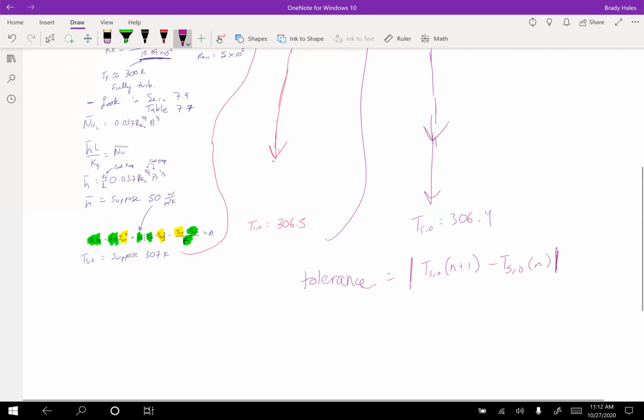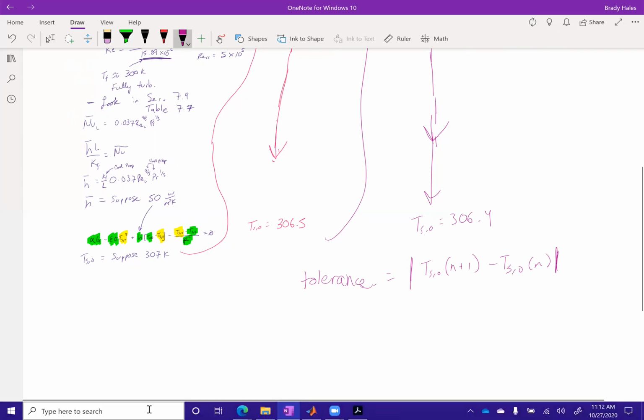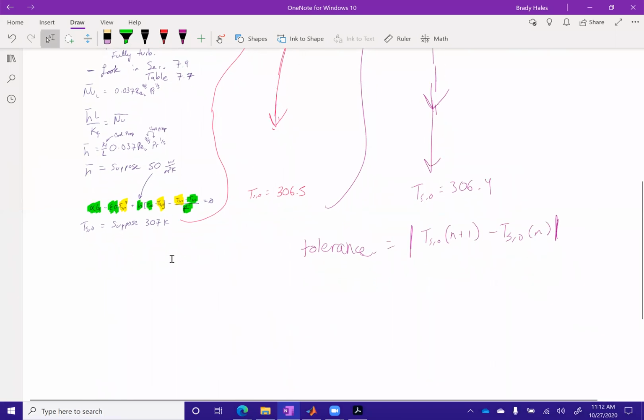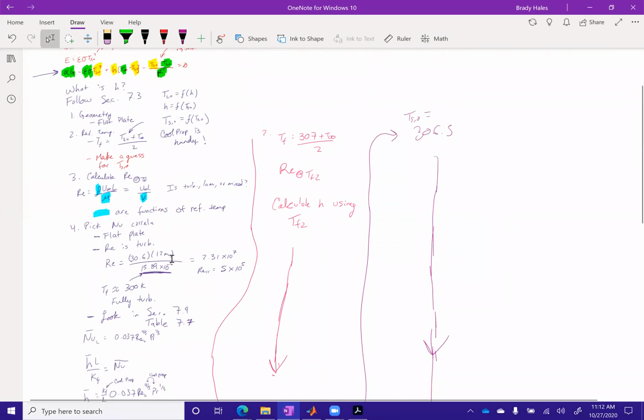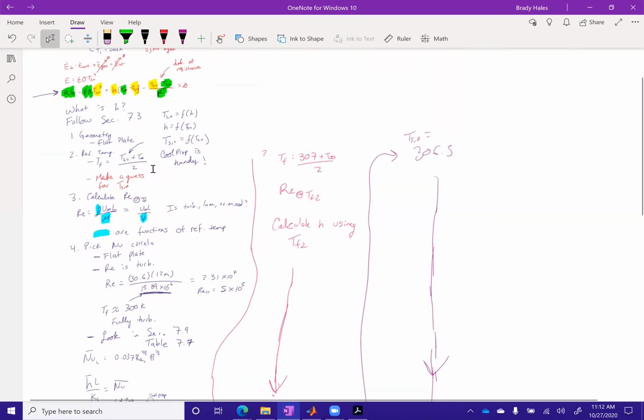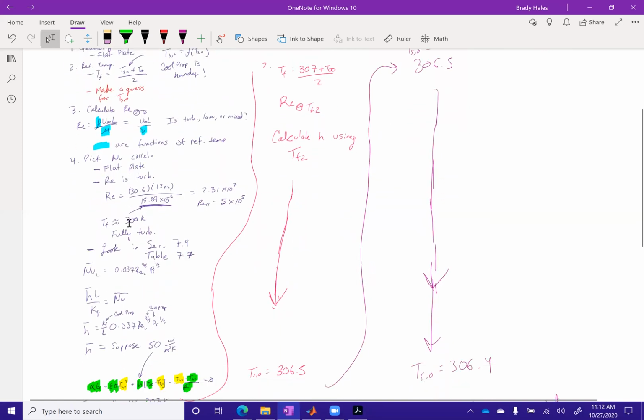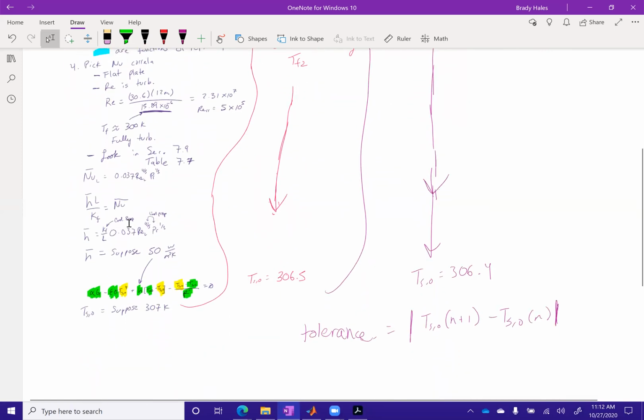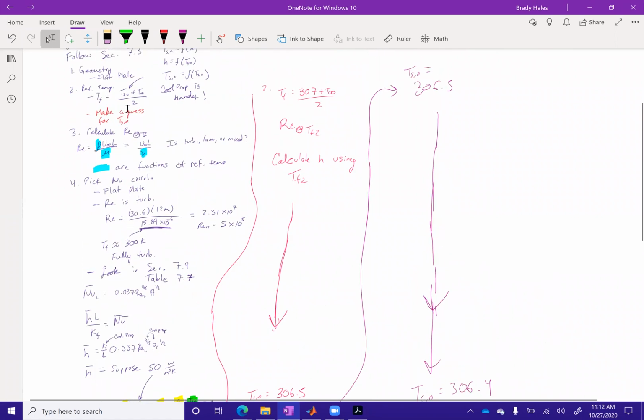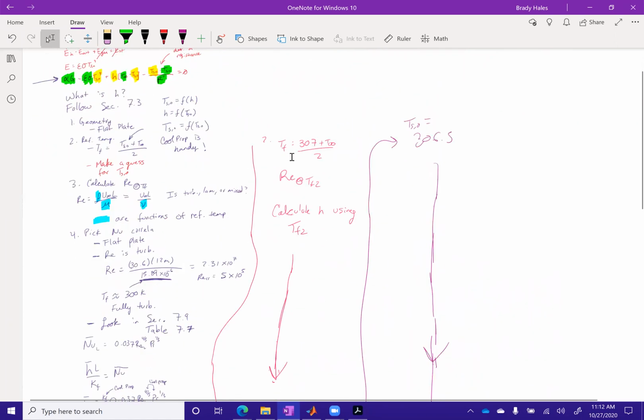So now I'm going to open up MATLAB and code this up, right? Because you can see where this really comes in handy with the CoolProp libraries is because your film temperature is changing, all of your properties change, right? So instead of running through this process by hand 3 or 4 times, you can put it in a while loop. Okay.